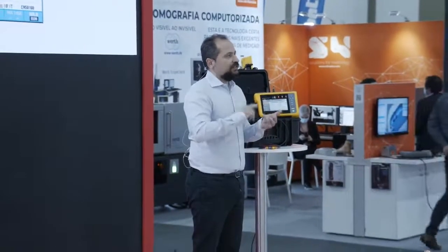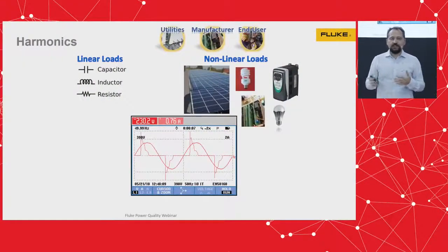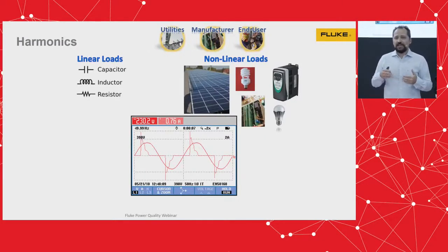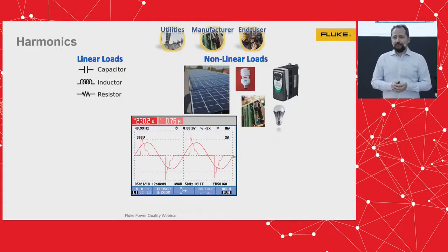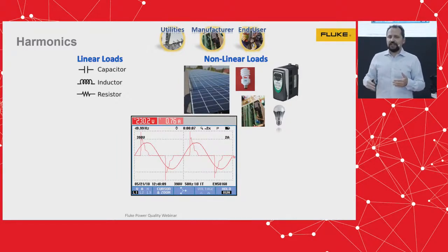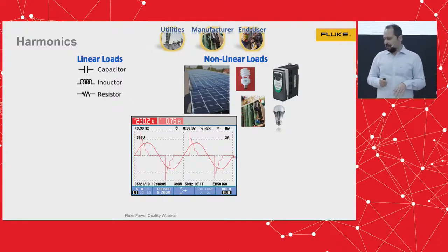Whether we have a rectifier, diode, or any semiconductor device that makes me work in DC instead of AC, that is introducing harmonics by default, which are high frequency components in my signal that have bad consequences for our power quality. They are heating up our electrical system, creating noise, creating vibration. All the issues that we were mentioning in many cases are related to harmonics.